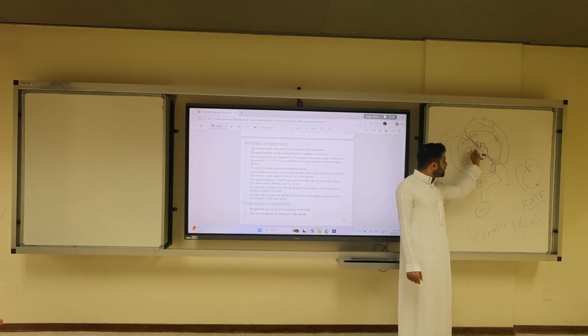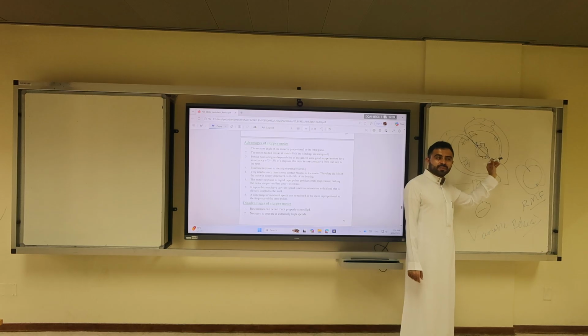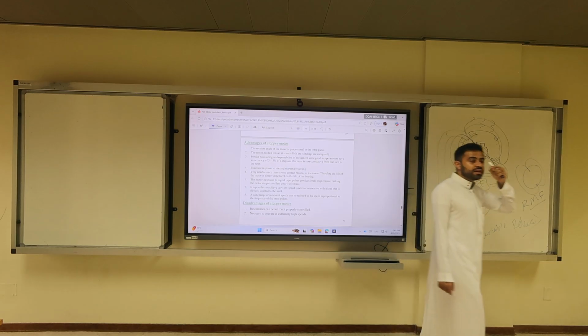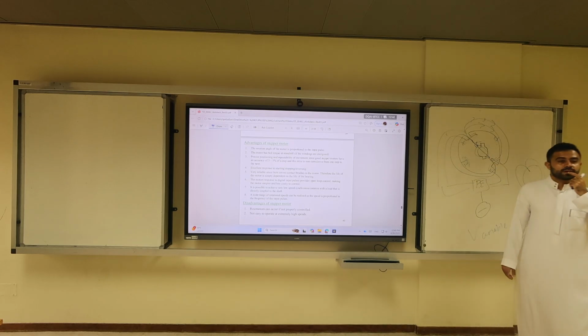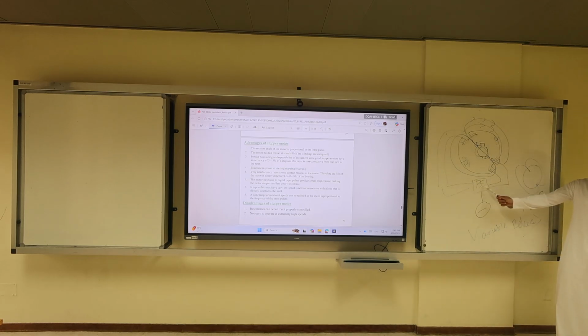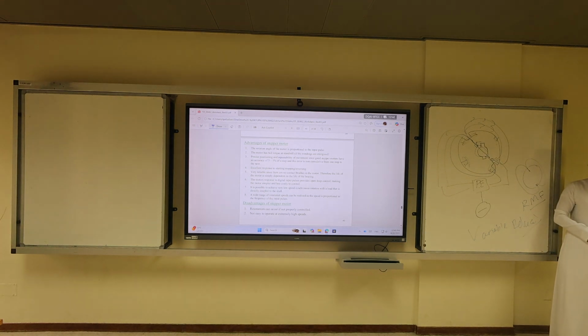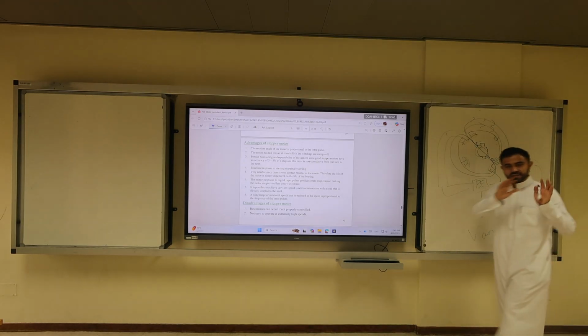That's a 90-degree stepper motor. But that's not realistic. How to make it successful? We add maybe 6 or 8. Reduce the angle. Now I can align them. Get it? Can I make it even more precise movement? Yeah, here comes the power electronics game. Can I energize 1, 2, and ignore 3? Yes. And we will see this in the stepper motor.